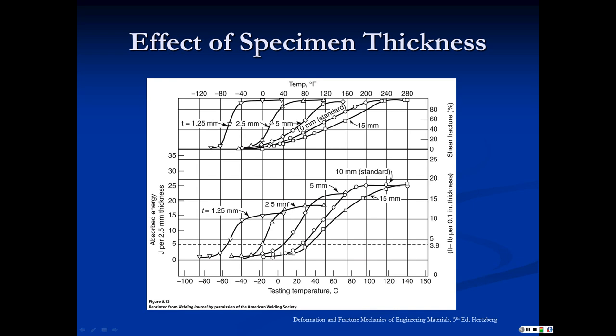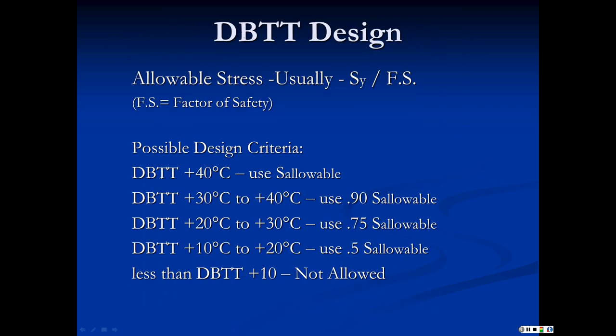And so you got a 17 degree shift from the true worst case behavior because you're at 10 millimeters and your material's not worst case until 15 or larger. So you could easily overwhelm this 10-degree margin and find yourself operating here when you probably shouldn't be working here at all, because you may be well into the brittle behavior.